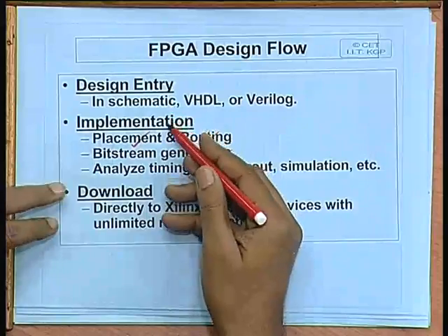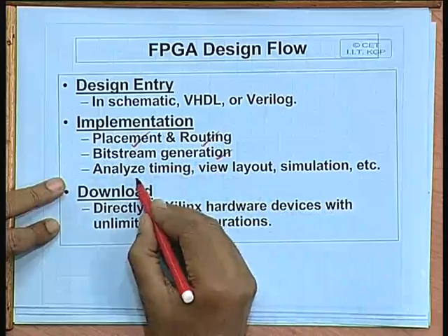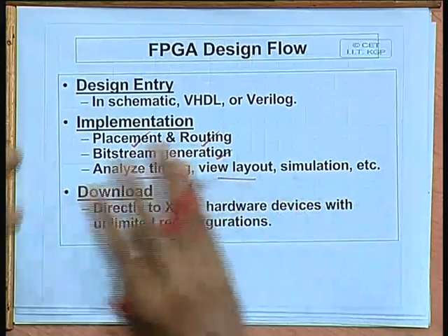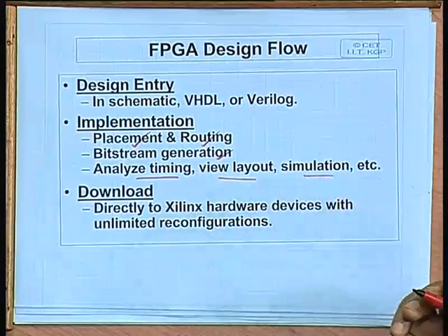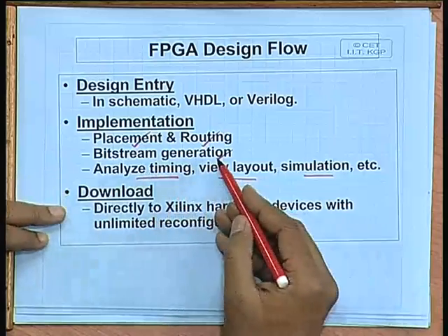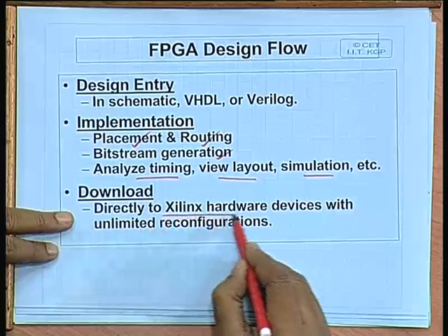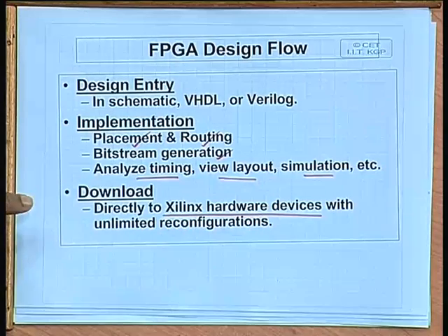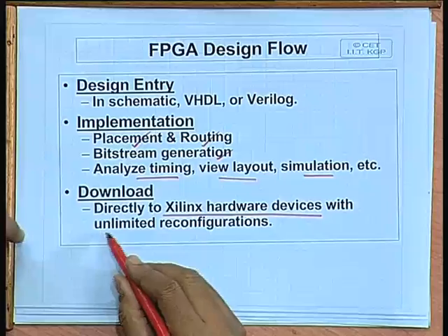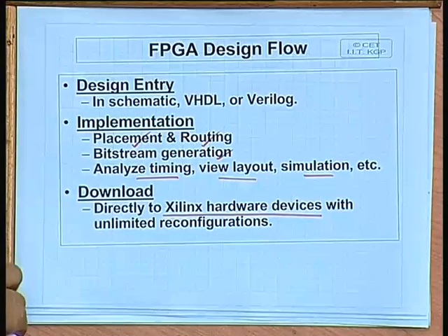And there are some tools using which you can analyze timing, see how the layout looks, and simulate, and finally after the bit stream is generated, you can download it directly onto the Xilinx hardware devices. Xilinx supported unlimited number of reconfigurations because they are based on static RAMs.